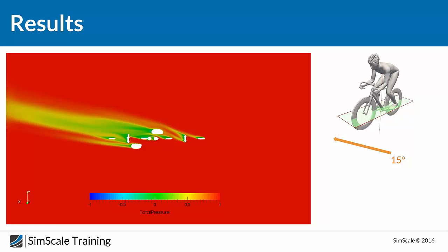But I think, Akram, we have a leading edge separation on the other side of the wheel, right? If you take a look. That's right. We can see here clearly that we have separation from this side, but actually later when we see the results, we will see that this design of the large tires will decrease the drag dramatically, but will increase the side force because of the large area. We will see this later in the next slides.